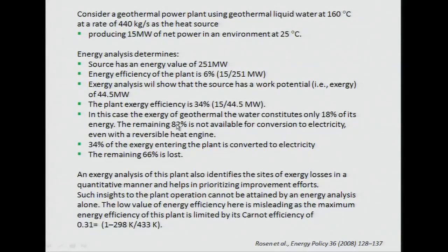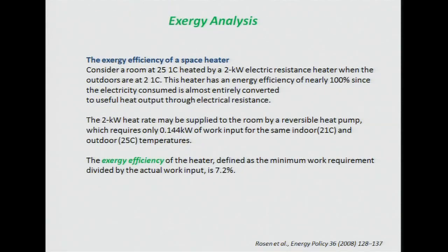But we learn a little bit more here. It doesn't mean to say it's better, right? Because here we're throwing away 66% of available energy. That's energy that was available to do work, right? In here, of that 94% of energy that didn't get used, not all of it was available anyway. So it's good to know how much, because then you know what you're limited to. You don't want to beat your brains out trying to get 78%, and you couldn't.